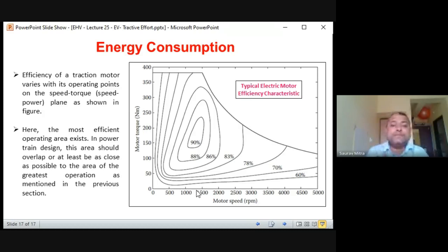So what we are trying to find is the sweet spot. What is the sweet spot? If the car can go up to 200 kilometer per hour, we can drive it at around 50 to 70 kilometer per hour. From this range we can find that. This 0 to 5000 maps to 0 to 200 kilometer per hour, so almost 20 to 30% of maximum speed. That means 20 to 30% of 200, which is around 40 to 60, 70 kilometer per hour. If we can drive at that speed, only then are we going to get maximum fuel efficiency.